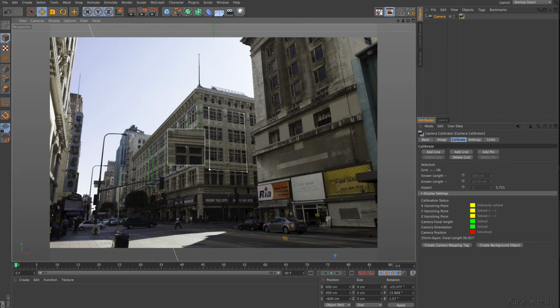So I do this very precisely and click to get green because that's the same, and then we need a red axis. And you can see now the Y vanishing point has enough information. All these green lines, now we have 4 of them, create somewhere a vanishing point. Maybe 1 or 2 are not really there, but 2 have met very precisely, and that gives me a value of 0.003, which is considered green. Perfect. So the red and the blue axes don't have this so far. They are yellow, they are solved somewhere.